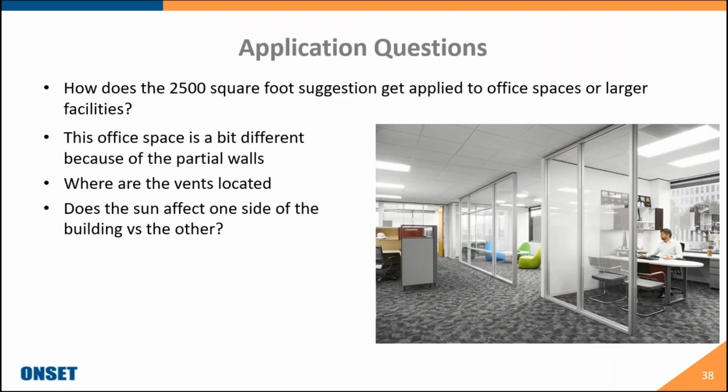And here, just to follow up on that last statement, here's an office space where it's not a big wide open space. You have several partitions up, glass walls, glass doors. This gets a little bit trickier for doing your monitoring, because now with it not being a wide open space, more than likely you're going to have to place several data loggers around this area, probably one in each of the glass offices. And then maybe again by the thermostat and also by where any of your HVAC vents are. It's always a good idea to locate where exactly those are as well before deploying.